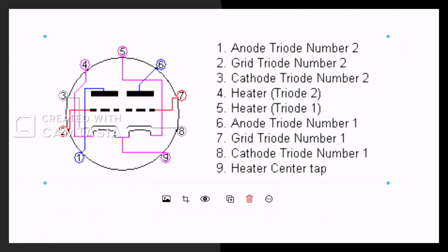After viewing either the datasheet or the schematic of the twin triode, we can see that it is indeed a dual chamber or dual element device with two anodes, two cathodes, two heater elements to loosen the electrons from the cathode, and two grids in two individual chambers. When working with this device, at first I thought that you could have a stereo or dual mono device being amplified. However, since we were reviewing the digital overdrive with an input gain and an output gain, typically what happens is that one stage of the triode will be cascaded in series, connected to the next stage of the triode.